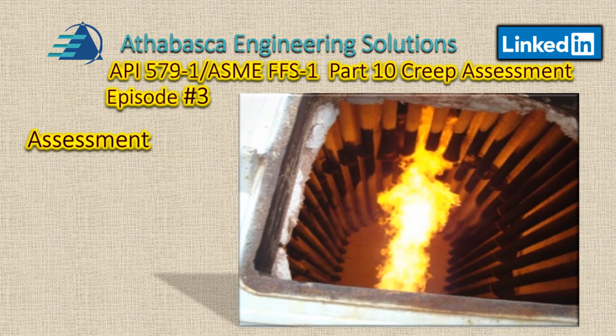The assessment done in Example 2 is a Level 1 assessment. In this assessment, we would be following the creep service procedures found in paragraph 10.4.2. And each component, like we've done in the last example, must be analyzed separately. In this example, there are straight tubes, and then there are two bends. We're going to look only at the straight lengths. The tube bends are located outside the firebox, so only the cylindrical tubes will be analyzed.